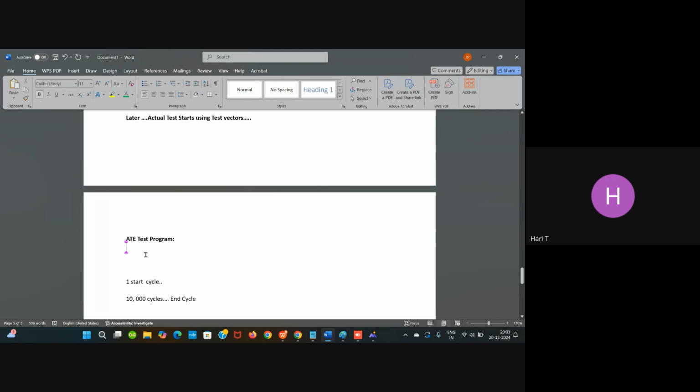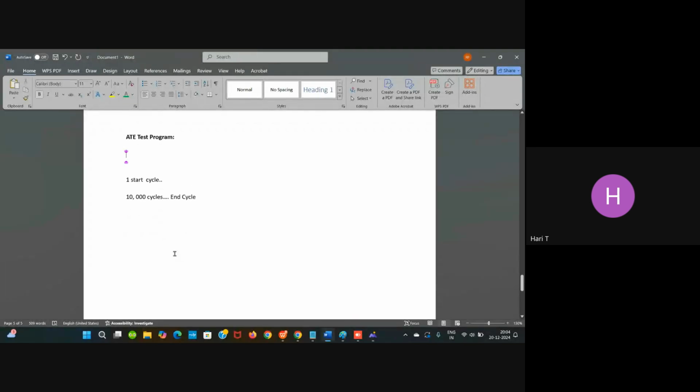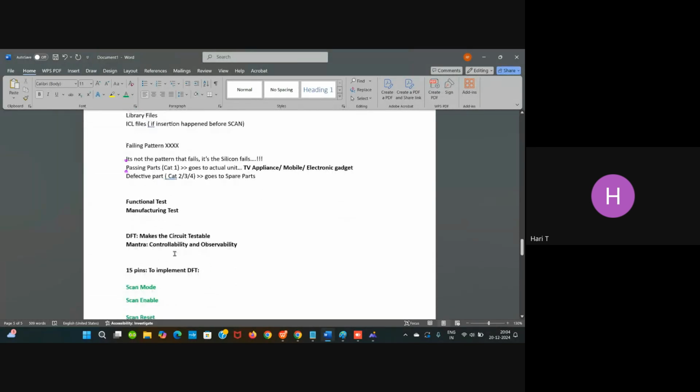During the testing program, there will be a mandatory protocol, like they should consider the chip specification. In the traditional RTL to GDS flow, the basic step is the chip specification right from the start. So engineers specify parameters such as at what temperature conditions or what clock frequencies the design needs to be tested. All parameters will be included in the test program. Okay, this is regarding the ATE test.